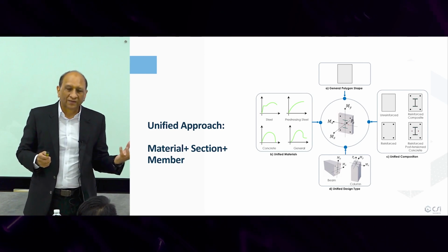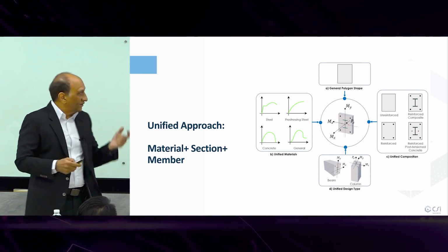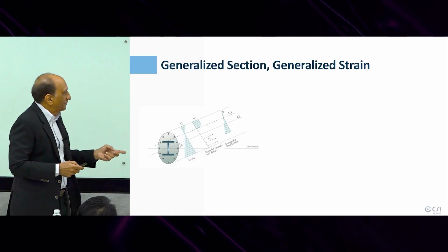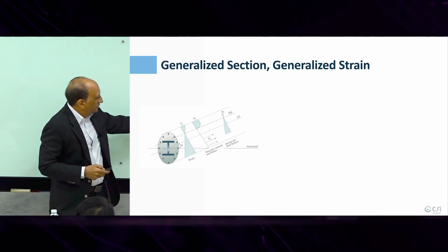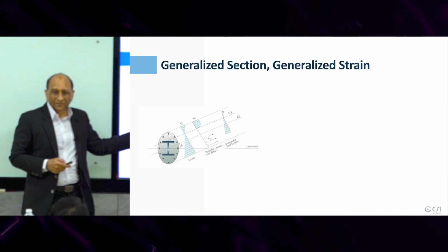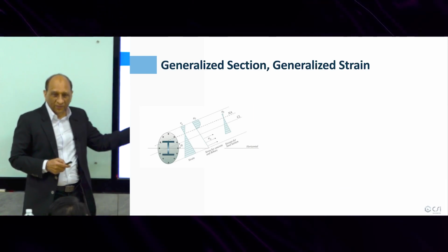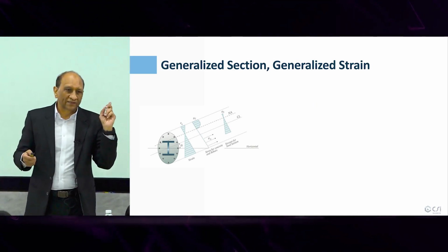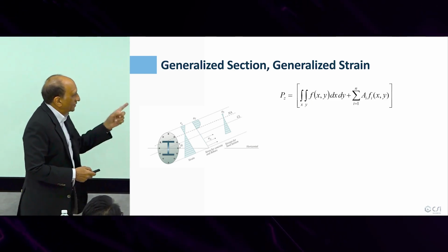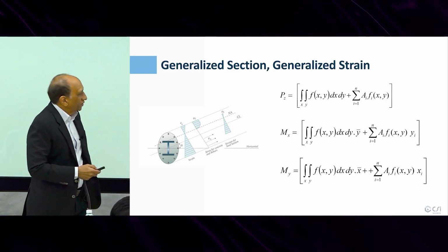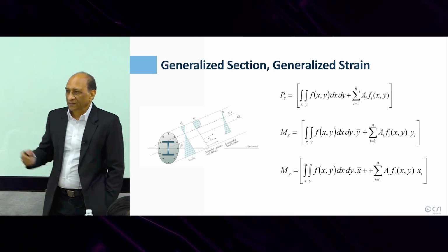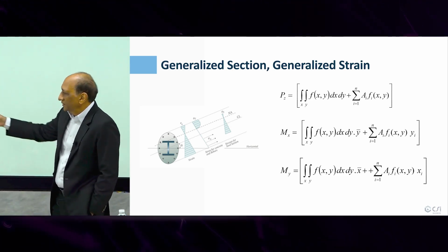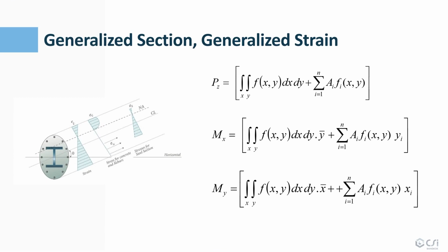So if we take this as our starting point and say, okay, this is our cross-section, then we can go ahead and deform it on a certain angular direction for a specified strain, any strain, starting with any strain, just like we did for the previous case. And then we can come up with these equations for the equilibrium of the stress resultant. So we can integrate all the stress resultants based on that cross-section, based on the material stress strain curve here. This is a strain diagram, this one, this one.